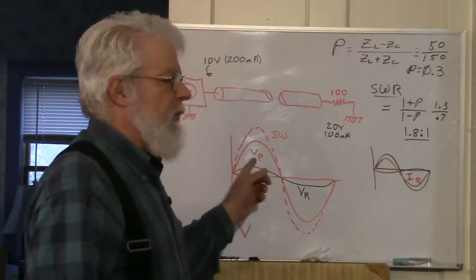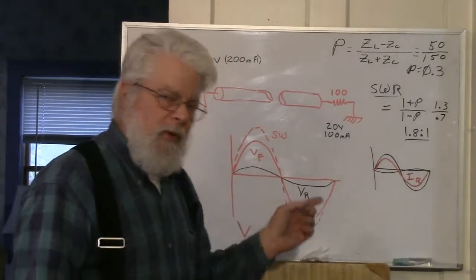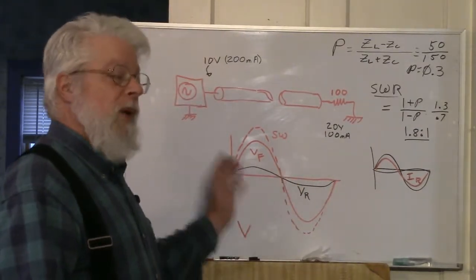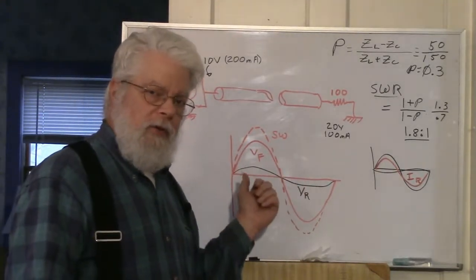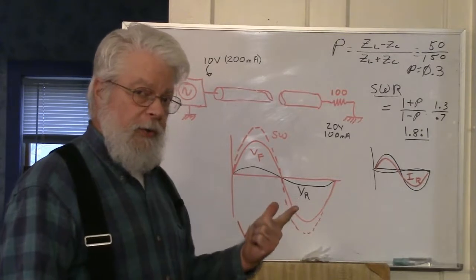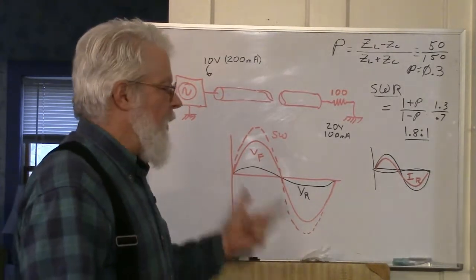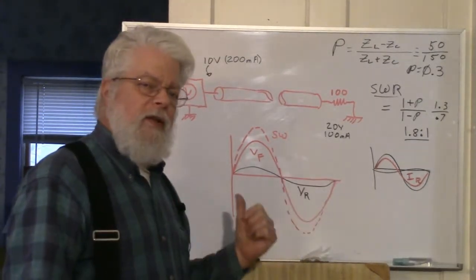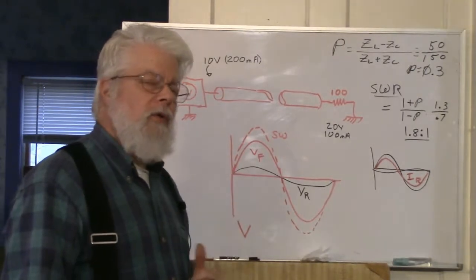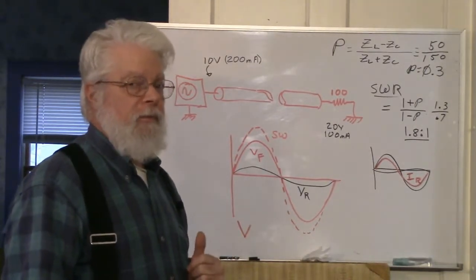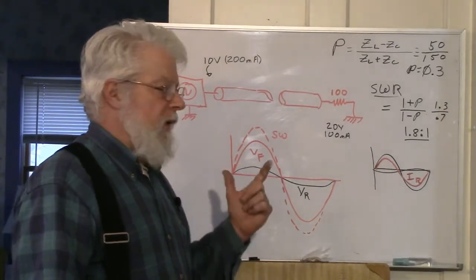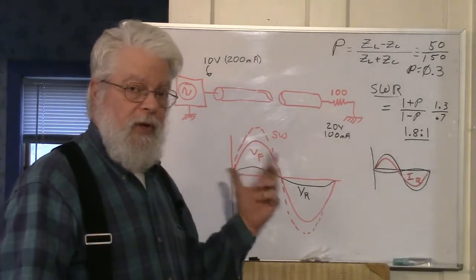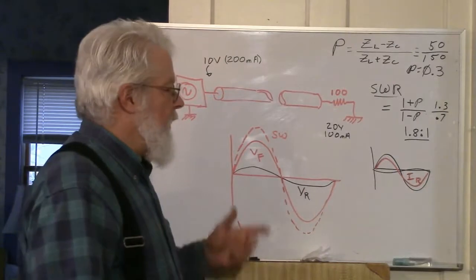regardless of anything else, the components of the reflected energy, meaning the voltage and the current, those two components, are always reflected back 180 degrees out of phase. It's a very important distinction, given the way we're going to be metering this.